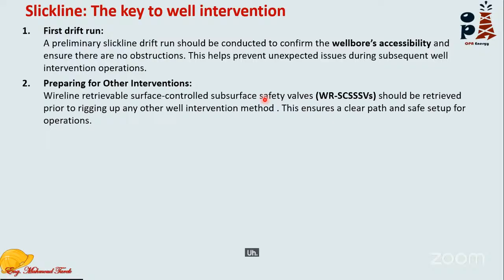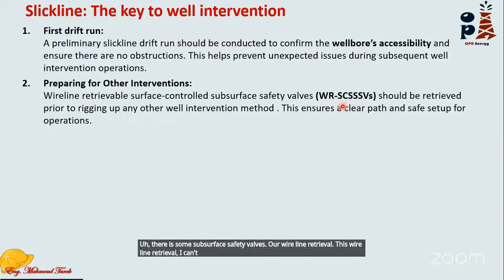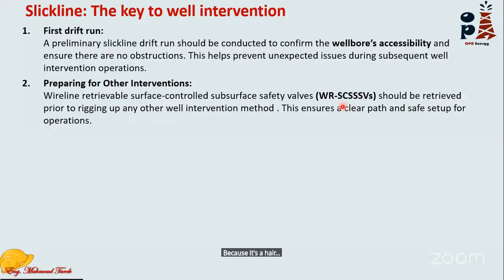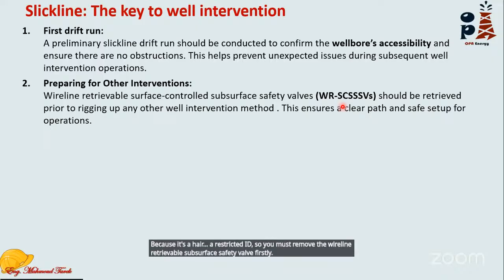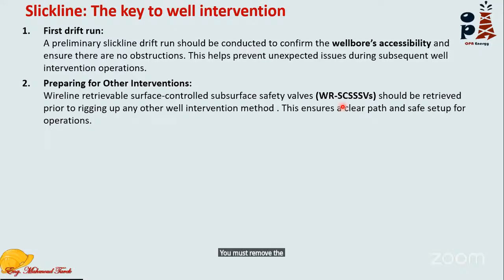There are some subsurface safety valves that are wireline retrievable. With this wireline retrievable valve, I can't go through it because it has a restricted ID. So you must remove the wireline retrievable subsurface safety valve firstly, before going downhole with any well intervention application.